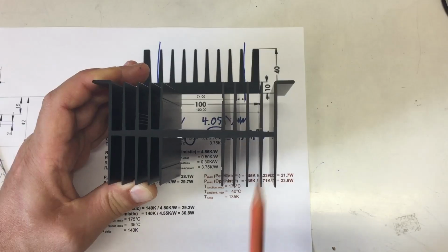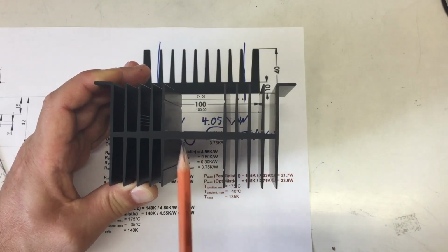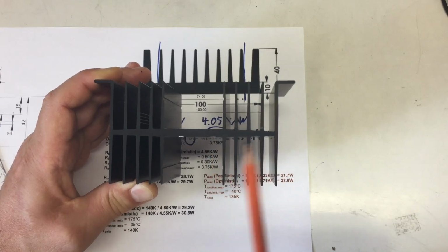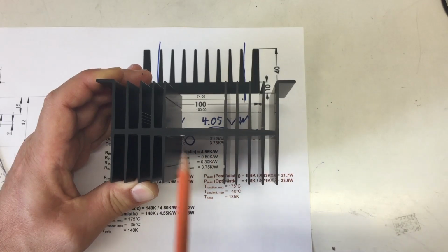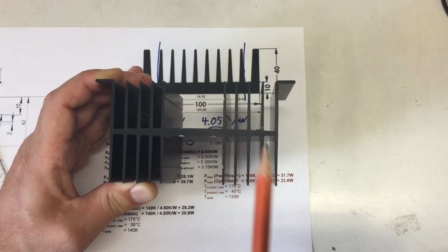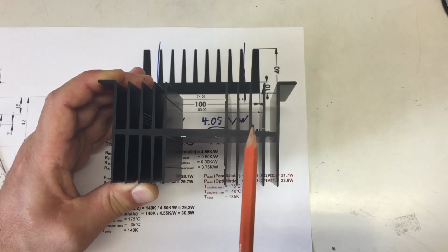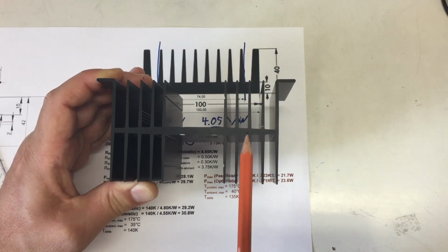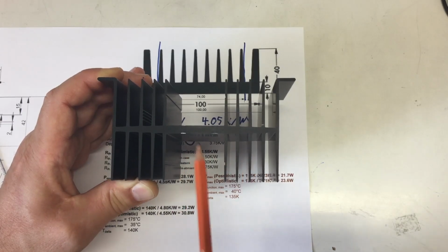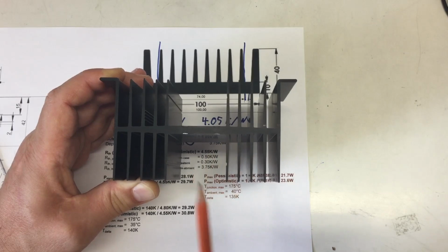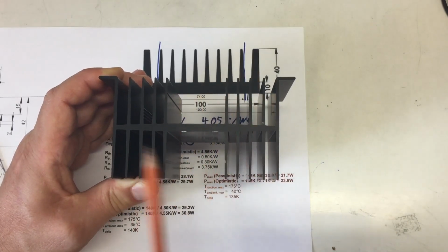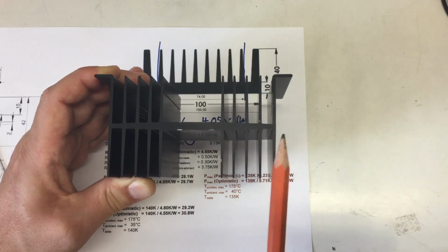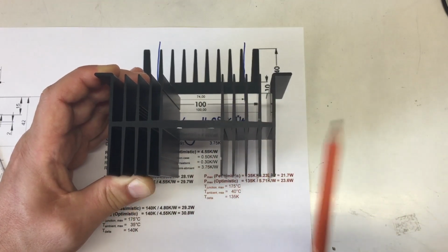And the reason for that curve being exponential or something like that is how these passive heat sinks work. They rely mostly on convection. There's also some heat radiated away in the form of infrared, but the bulk of the heat is transported away by convecting air.